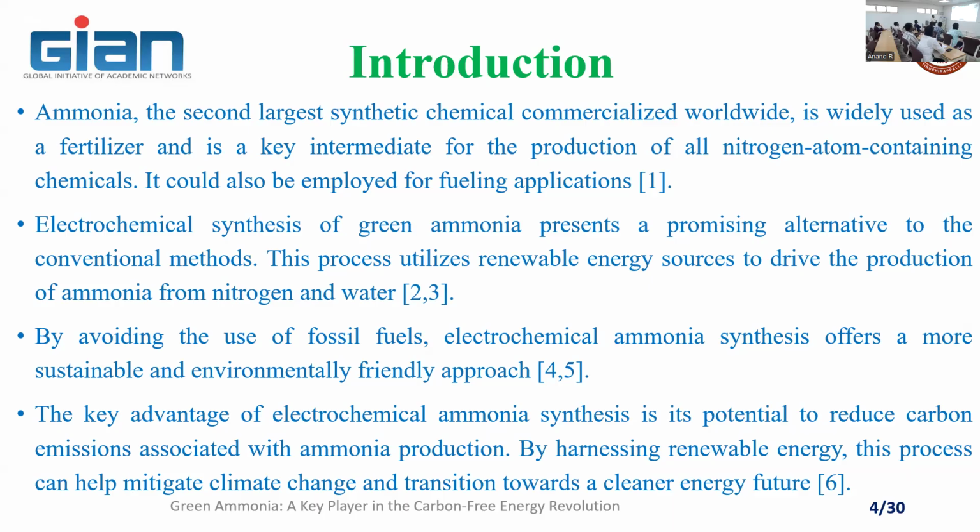So by maintaining the conditions in the Haber-Bosch reactor at a temperature of 350 to 450 and a pressure of 250 to 350 bar, with proven catalysts, they have tried several catalysts, thousands of catalysts, and finally came up with a ferrous kind of catalyst which is able to give the maximum generation of ammonia, about 85 to 90%. That is the proven method.